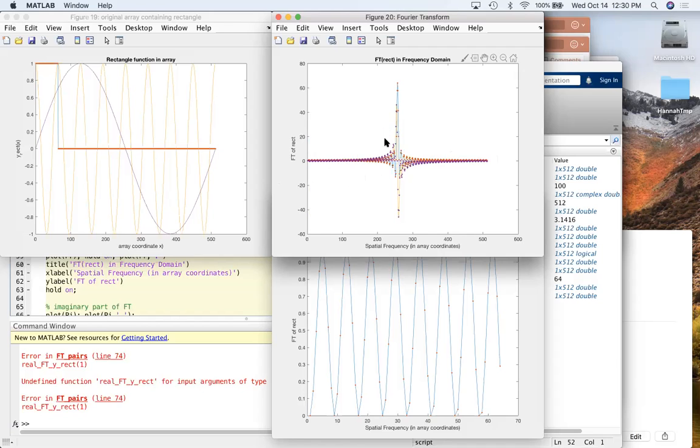So it's sort of a convenience thing in many ways to plot it like this, because now you see your DC signal or your low frequencies at the center of your field of view of looking at the Fourier transform. So you'll see this done a lot, where the Fourier transform gets centered after the digital Fourier transform is taken, you'll recenter the Fourier transform to look at it like this. Right? Okay.